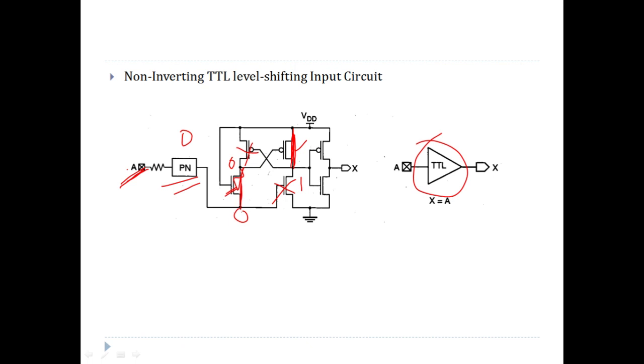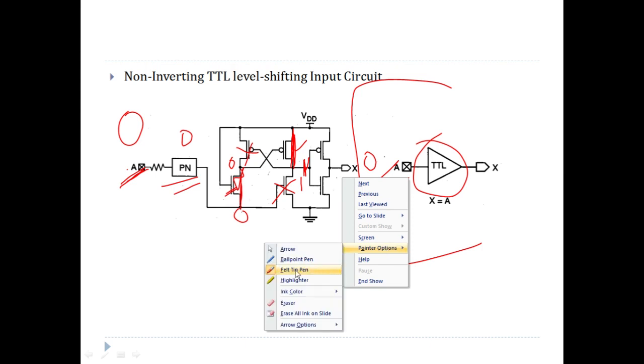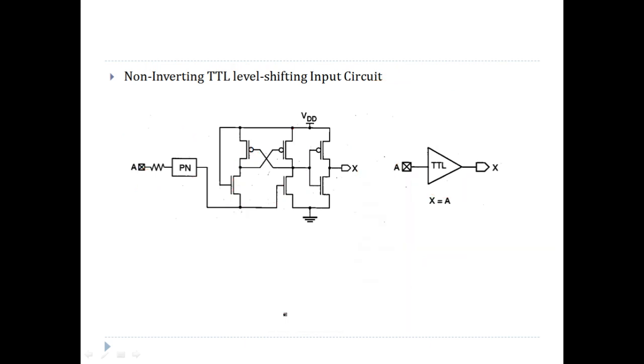to our assumptions. And then the VDD is applied at the input of this inverter, which is 1 volt, and then at the output you will have 0 volt. So basically the logic which you have implemented using MOSFET will get 0 as an input. So we are expecting the input to be 0, and the output we got is 0. So it basically has overcome the disadvantage of the simple inverter, that the input is in its real form and not in the complemented form.